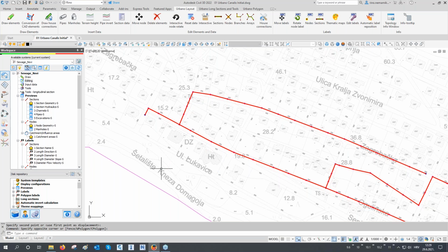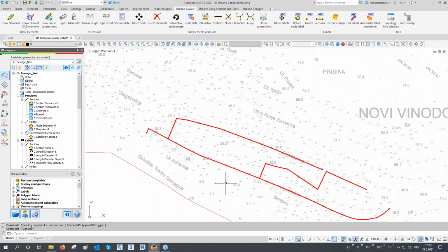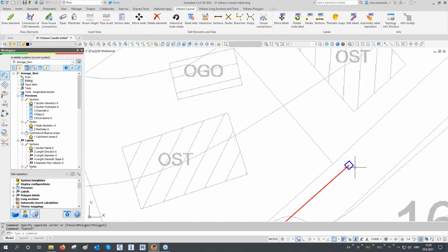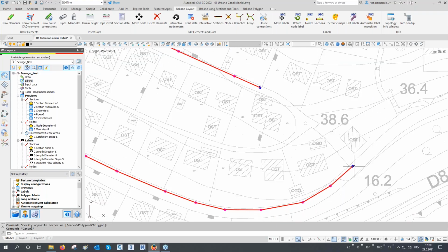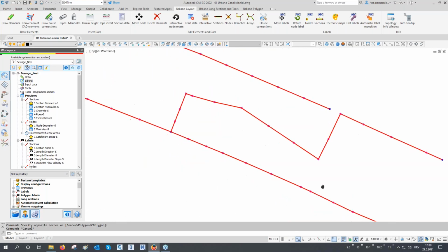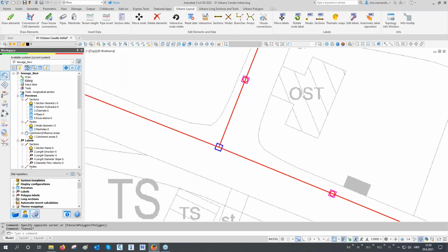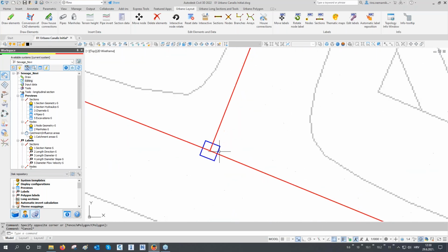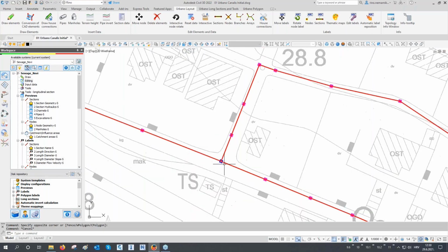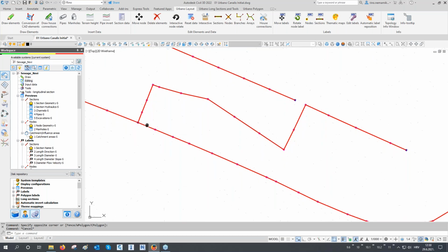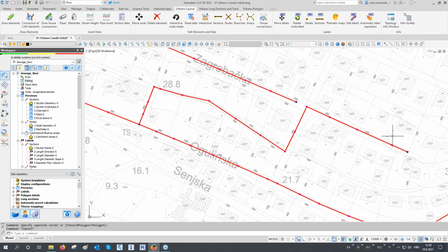Okay, so that is rule number 2 to know. Now we draw this system, and I will tell you what the main nodes and the plain nodes are. Basically, all the first nodes of the system, the last nodes of the system, and also the branching nodes of the system are called in Urbano main nodes, and you can see they are shown in a different color. Everything in between, starting, ending, or branching, is called a plain node.